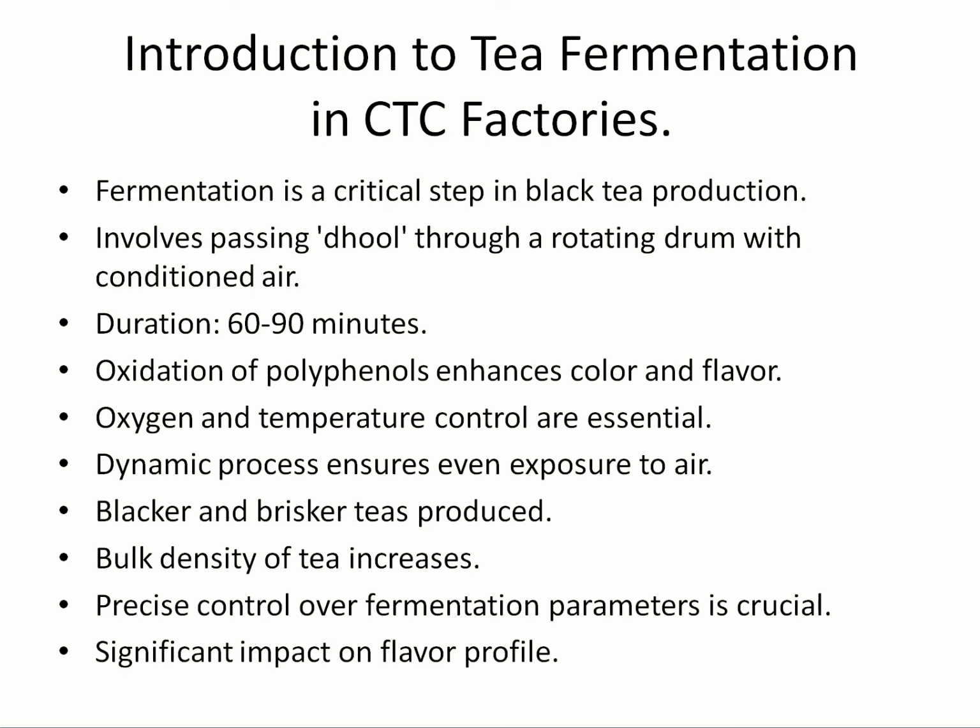Introduction to tea fermentation in CTC factories. Fermentation is a critical step in black tea production. It involves passing dhool through a rotating drum with conditioned air. Duration is 60 to 90 minutes. Oxidation of polyphenols enhances color and flavor.